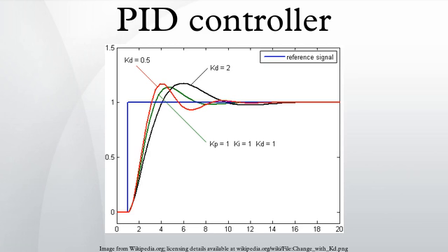Manual tuning. If the system must remain online, one tuning method is to first set I and D values to 0. Increase the P until the output of the loop oscillates, then this should be set to approximately half of that value for a quarter amplitude decay type response. Then increase I until any offset is corrected in sufficient time for the process. However, too much I will cause instability.